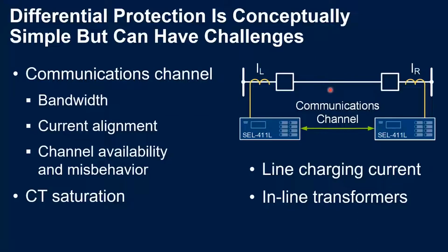Besides that, we also have to take into consideration what happens when one of the CTs saturates. Also, the phenomena of line charging currents, and what happens when they have transformers inside this protection zone, this transmission line. We'll take care of all these points through the presentation.